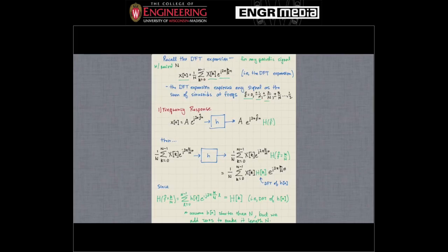The DFT is a way to express any discrete time signal as the sum of sinusoidal signals. When we looked at the DFT before, we said it was for a finite length discrete time signal. So it's also true for a periodic discrete time sequence. Remember, we could interchange periodic and finite duration just by truncating. If we had a finite duration sequence, we could turn that into a periodic sequence just by repeating it back to back.